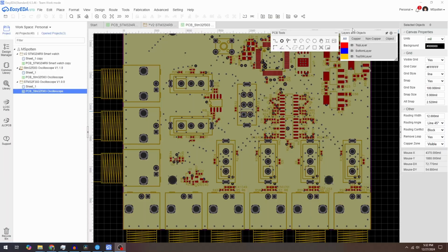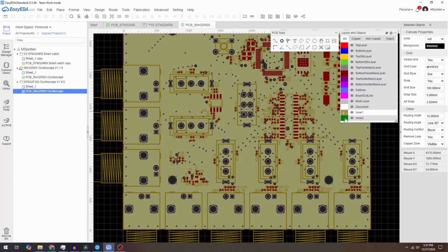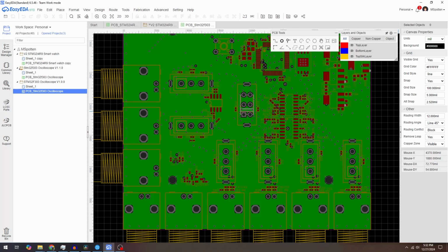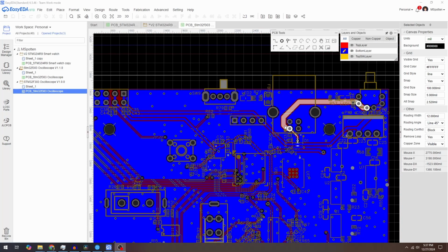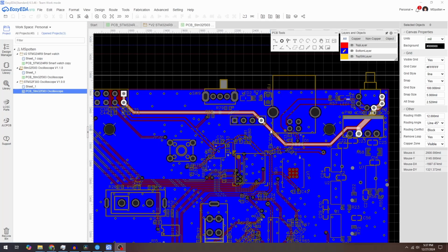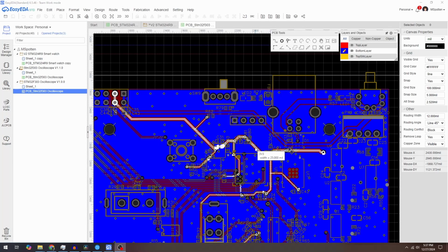But with that in mind, I designed my board with the 2 inner planes being ground and ground, connected often with shorting vias, with the top and bottom fill also being ground, and the power traces running on the bottom and the top of the board.